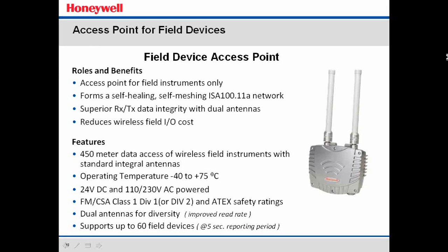The instrumentation. What does the transmitter do? It measures and wirelessly transmits data in industrial and hazardous environments. Configurable data routing, we talked about that. The data routing as well as the update rates are individually configurable per transmitter, meaning there's no concept of a zone or a group or an area. One is not dependent on the other. If I'm making one a router and it's at 10 seconds, it can route a 1-second update rate transmitter. At the functionality level, it's not a problem.